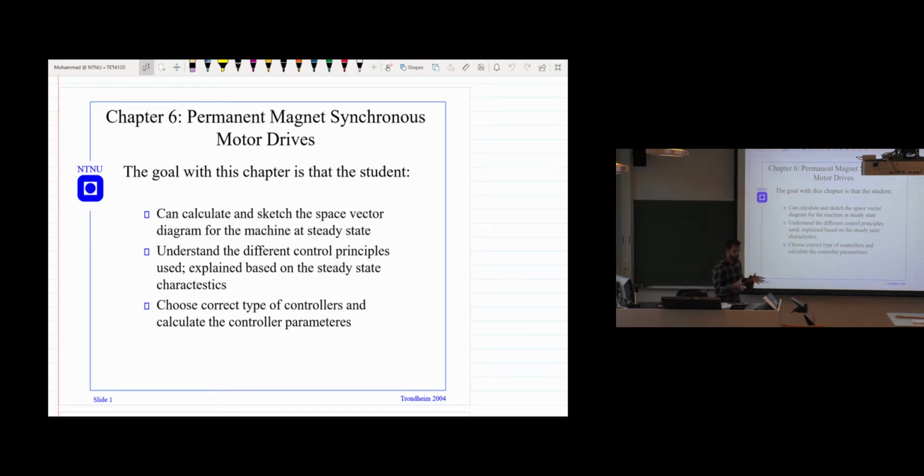So what you are doing is, you have the model, the control that you implemented in the control card. That's what you see in the lab. We have this control card, and you can implement the control there. The physical machine is a real machine, and from the machine you get the voltage, current, and speed by different sensors and put them back to the control card. So in the emulator lab, instead of a physical machine, you have the mathematical model of the machine inside the control card, and you are getting the current and the voltage from the mathematical model and giving them back to the control.